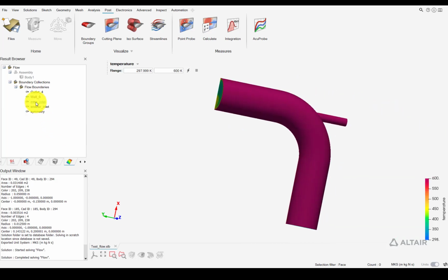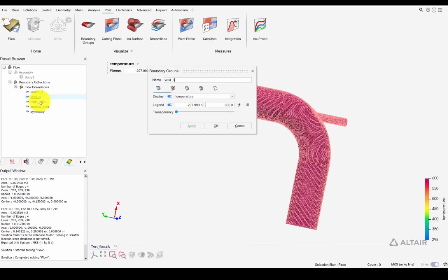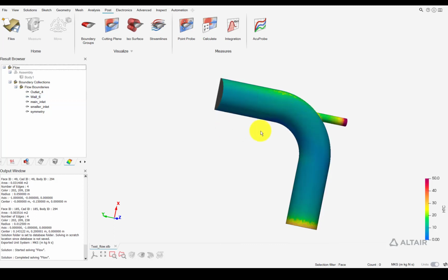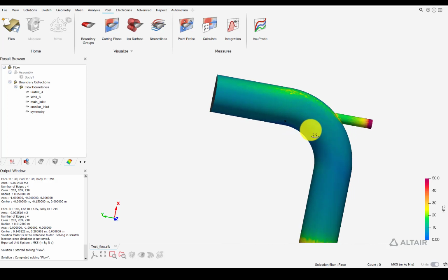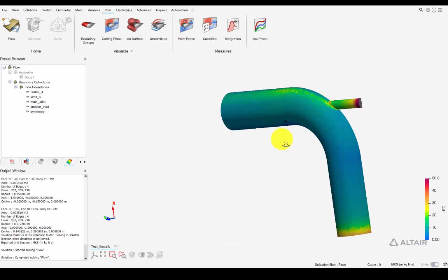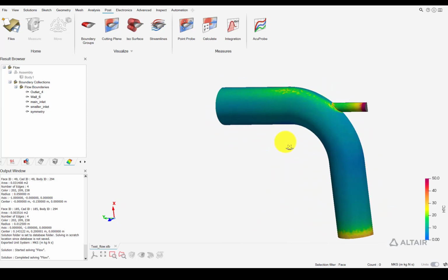And then we'll go to wall, drag down the menu, see the HTC variables that we just created. We put that as 50. Click display. So at this point, we have created a contour out of the HTC calculated by user specified heat flux.